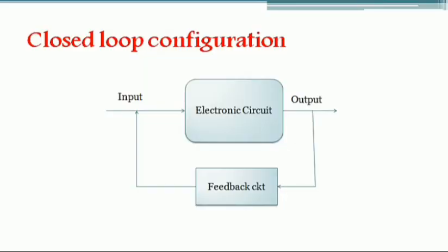The positive feedback circuits are used only in oscillation applications. Oscillators, multivibrators, in that case we use a positive feedback circuit. So depending on the application, we design this feedback circuit. For linear applications we use a negative feedback circuit, and for non-linear applications we use a positive feedback circuit.